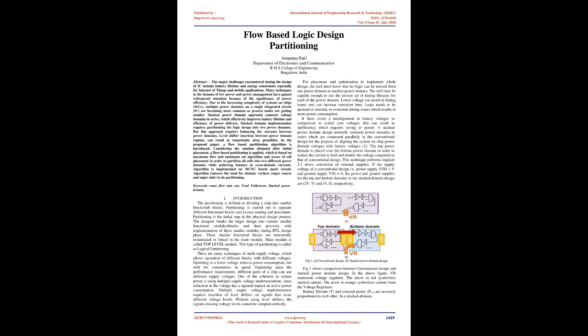Due to the increasing complexity of systems on chips, SoCs, multiple power domains on a single integrated circuit, IC, are becoming more common as process nodes are getting smaller. Stacked power domain approach connects voltage domains in series, which effectively improves battery lifetime and efficiency of power delivery. Stacked domain implementation requires partitioning the logic design into two power domains. But this approach requires balancing the currents between power domains. Level shifter insertion between power domain regions can result in remarkable area penalties.